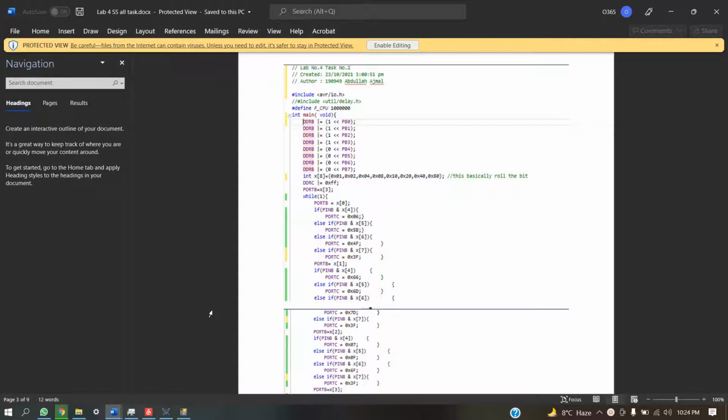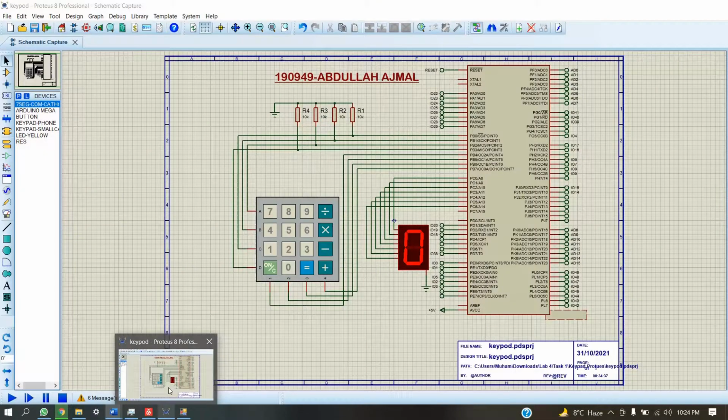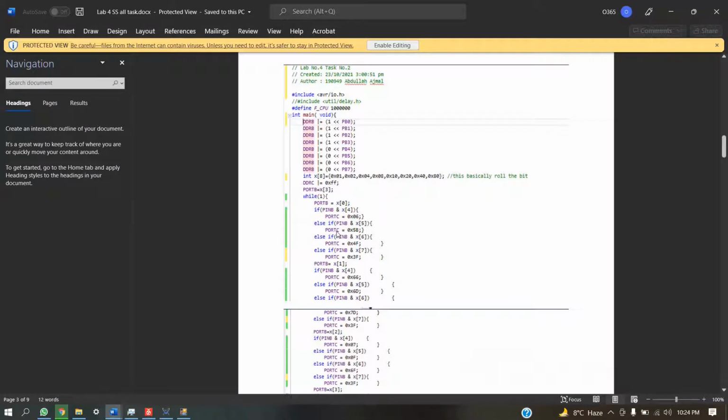So basically we can represent these digits using 7 segment display, and in this lab we are implementing a hex keypad with 7 segment display. So what we are doing, we are implementing a hex keypad which has buttons like this from 0 to 9 or 10, whatever, so numbers up to 15, and when we press the button it will display that particular value on our 7 segment display. 7 segment display accepts values in the form of BCD or in the form of 8 bits.